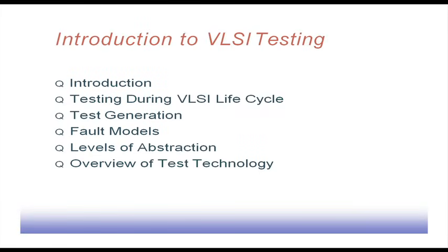So, we may get the entire PCB on a single chip, giving rise to system on chip type of architecture. So, that way, at which level we are attacking these faults, at which level we are trying to address this fault, that gives rise to these levels of abstraction. It may be easy to attack the system behavior related faults at a much higher level compared to, say, transistor level, whereas when we are talking about individual lines being short or individual lines being open, it may be better that we talk at a much lower level.